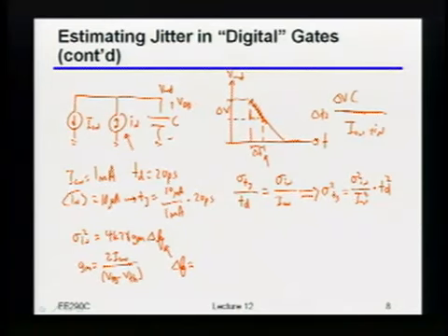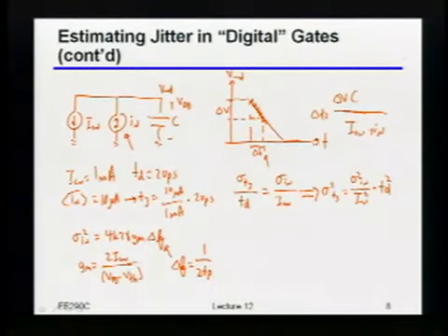In the frequency domain, that becomes a sinc filter. When you do that integration, which you just integrate from 0 to TP, the delta F you will get is simply 1 over 2 TP. Nice, simple result. Does this kind of make sense to people?